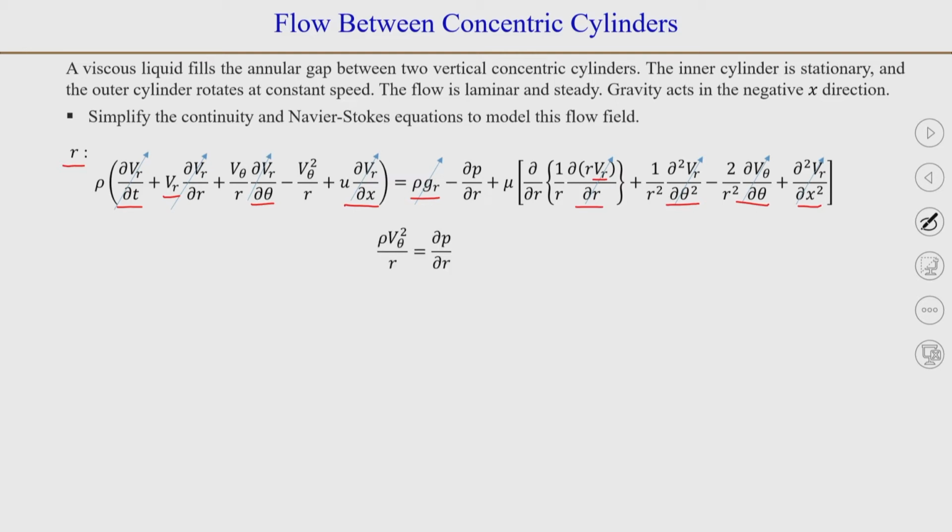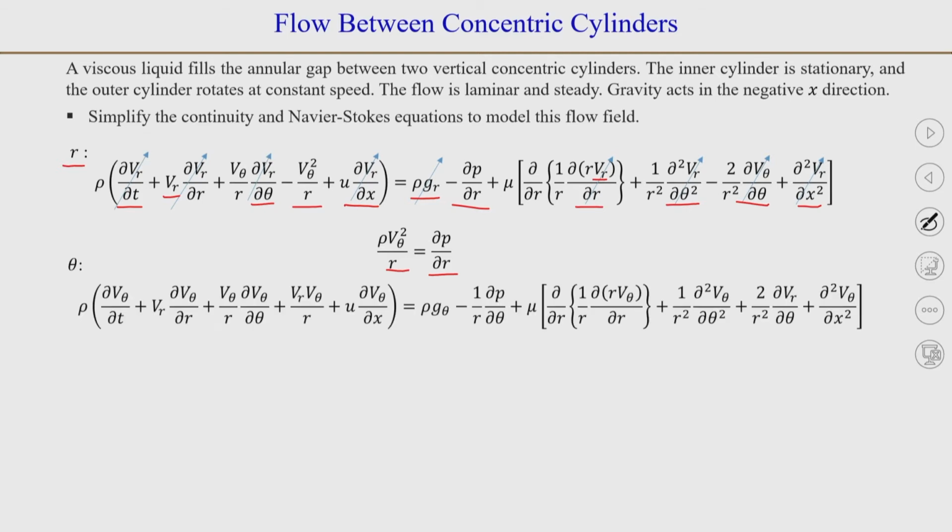So, what we have from this is the two terms which we are left with. So, that says ∂p/∂r is equal to ρ v_θ² by r. So, there will be a pressure gradient because v_θ will be non-zero. So, we will have a pressure gradient along the radial direction, which, if you look at it, resembles the centrifugal force. Okay.